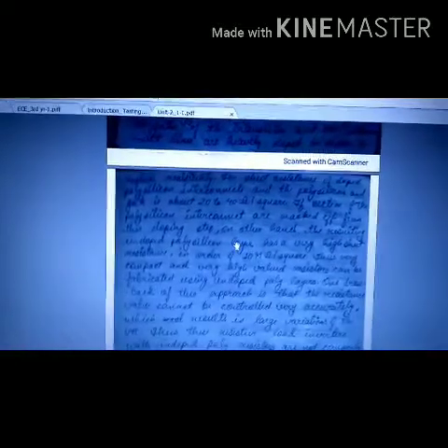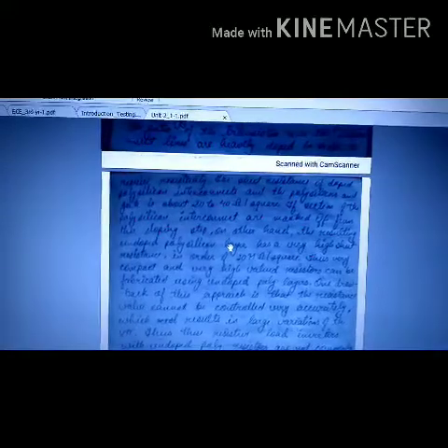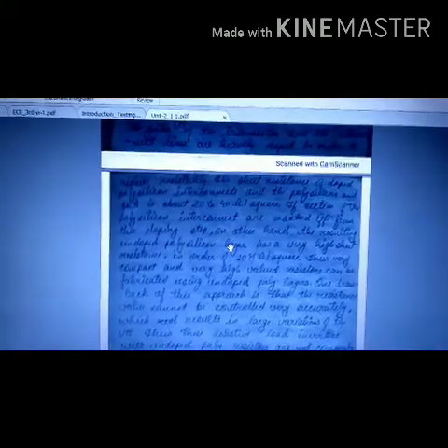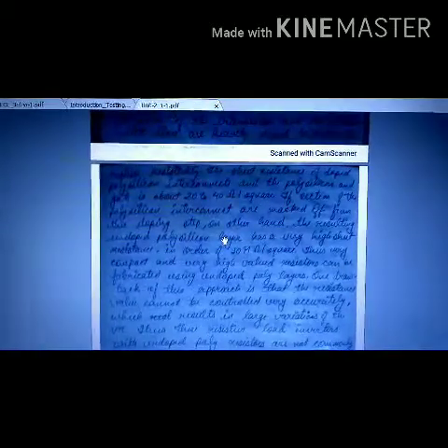So the required 10k ohm resistance can easily be formed depending upon the doping levels of the polysilicon. A very compact and very high value resistance can be fabricated using an undoped polysilicon layer.